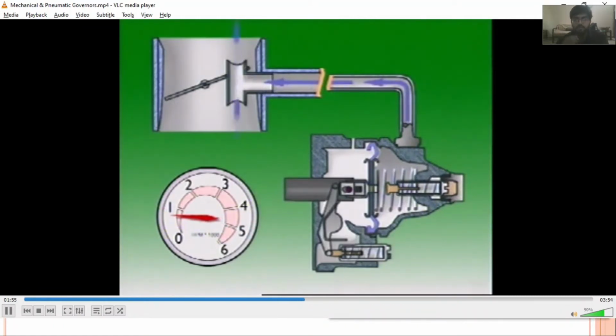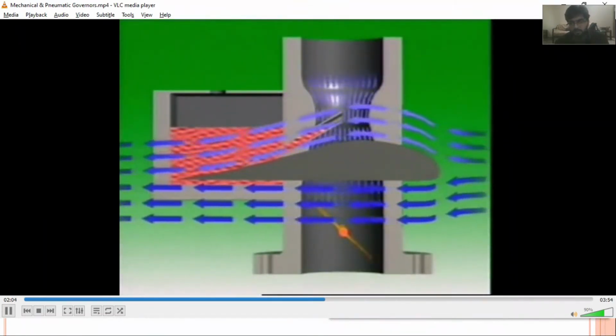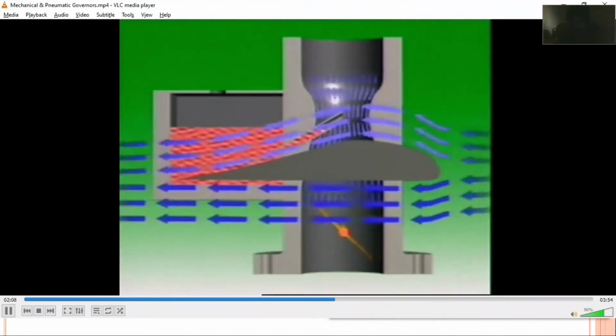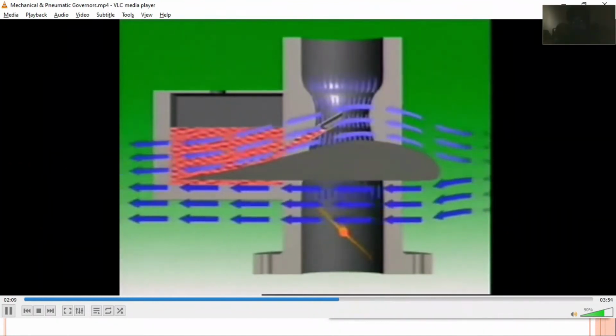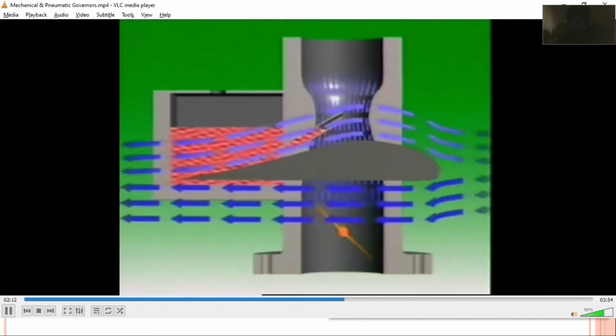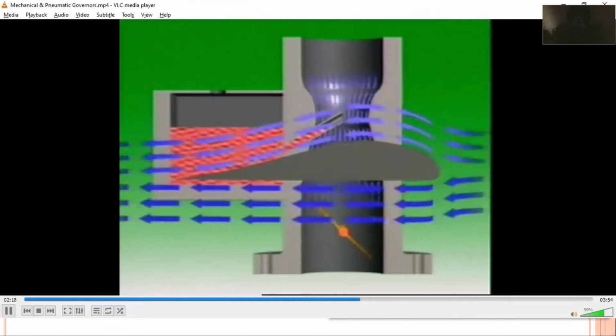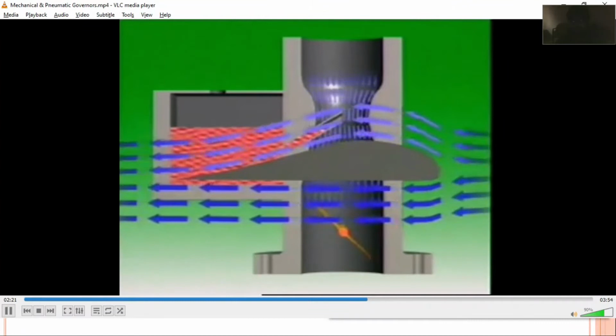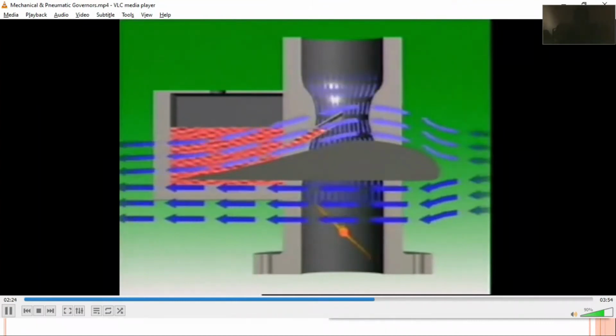The Venturi is narrow and shaped so the air speeds up as it passes through. A similar effect occurs around aircraft wings. The shape of the wing section speeds up the airflow over the top of the wing and creates a low pressure area there, lower than the atmospheric pressure below. The result is an upward force that provides lift for the aircraft. The shape of the Venturi is designed to apply the same principle.